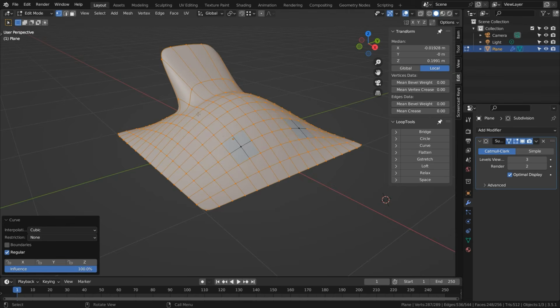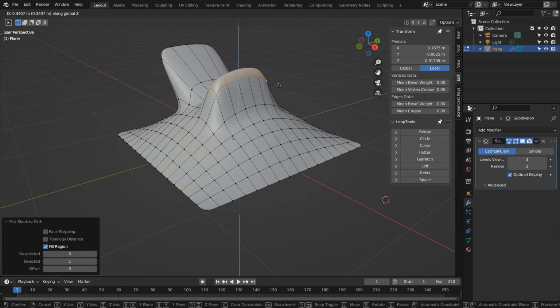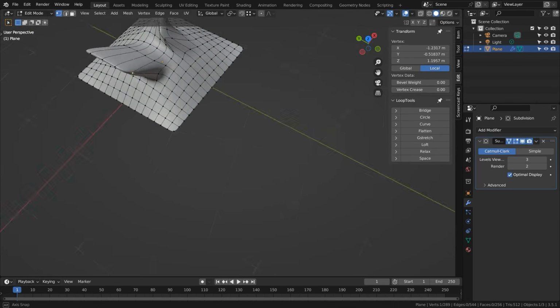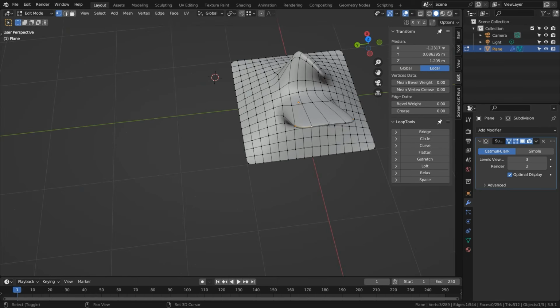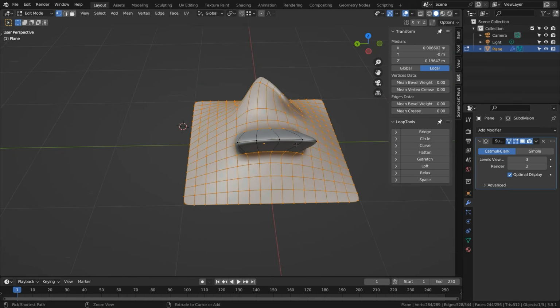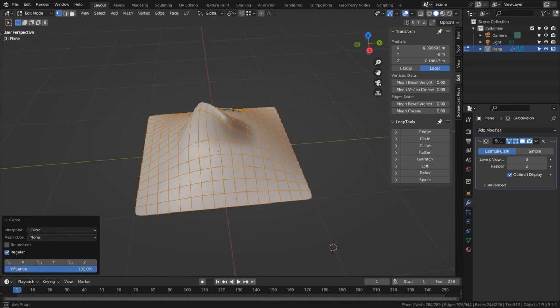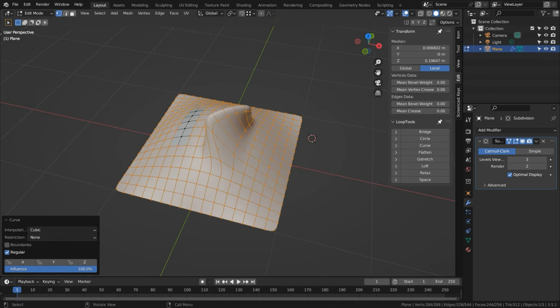And we can continue shaping this surface and making changes, and we will always have the ability to reduce or remove features as we want. Just selecting a few points we don't like, then pressing Ctrl and I to invert the selection and use the curve button. There are all sorts of reasons vertices can be moved out of place on a mesh, and with the curve tool, it's very easy to rebuild complex curvature.